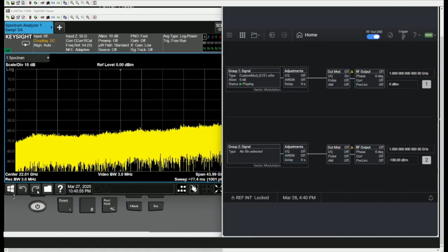In this quick video, I'm going to walk through different measurement methods when you want to measure a modulated signal, for example, a 40 MHz wide bandwidth 16 QAM signal. What I have here on the right side is a two-port N5186A new MXG. It's a bit different from the previous video because this is a two-port option. Nevertheless, the whole setup will be the same.